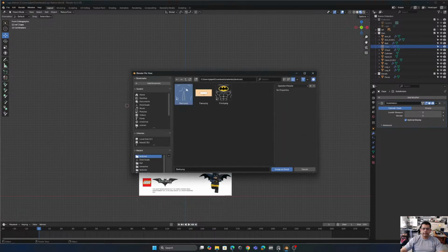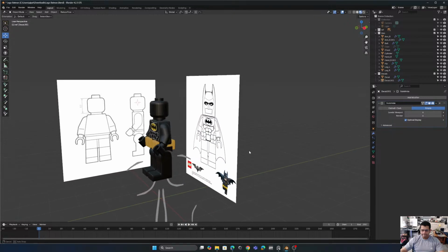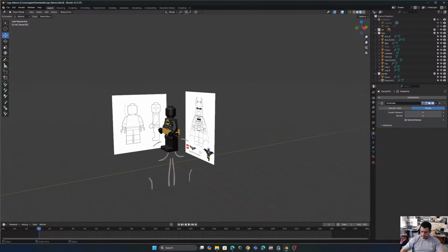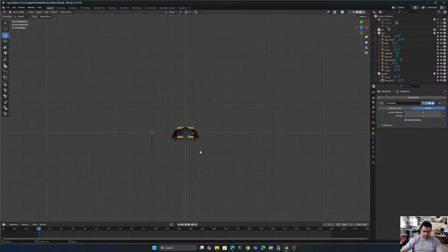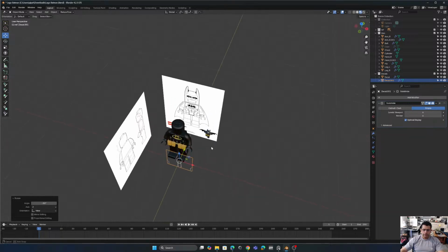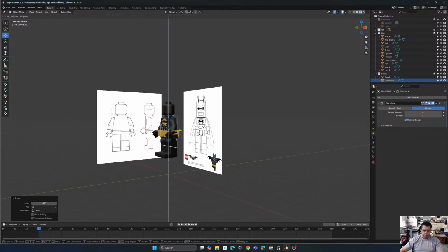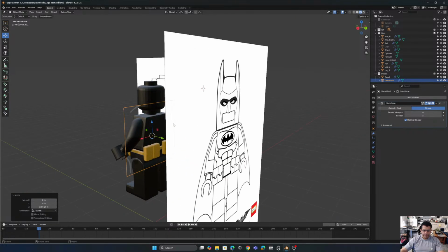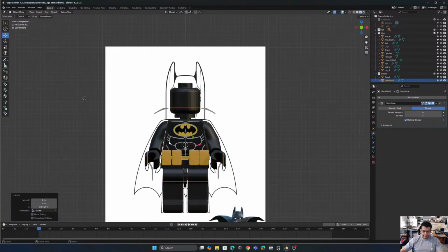We're gonna select the back. We're gonna go to the top view with 7, select the image as decal. We're gonna scale it a little bit to try to match the size. We're gonna press R to rotate, Control to move in the angles, try to match the front view. We're gonna put it in the top. We're gonna scale it, trying to match the size of the shape.